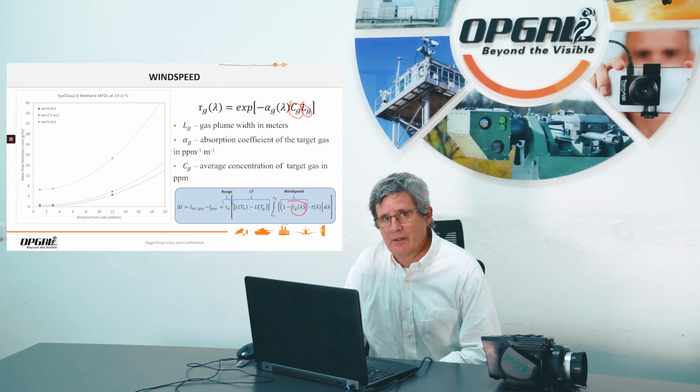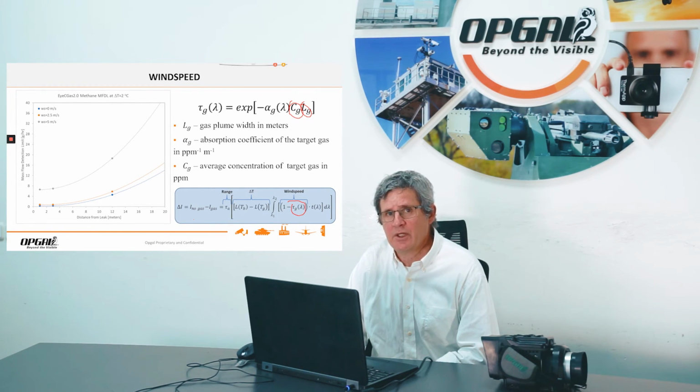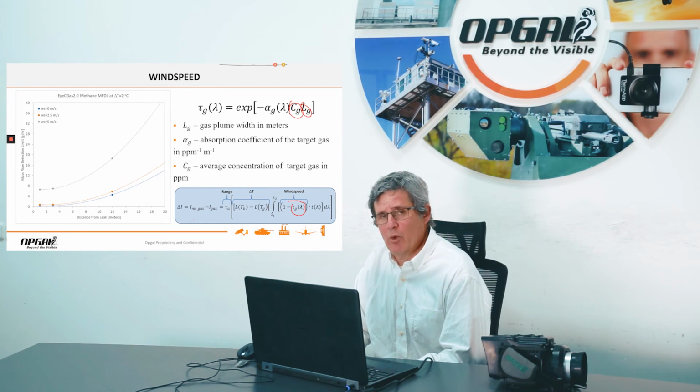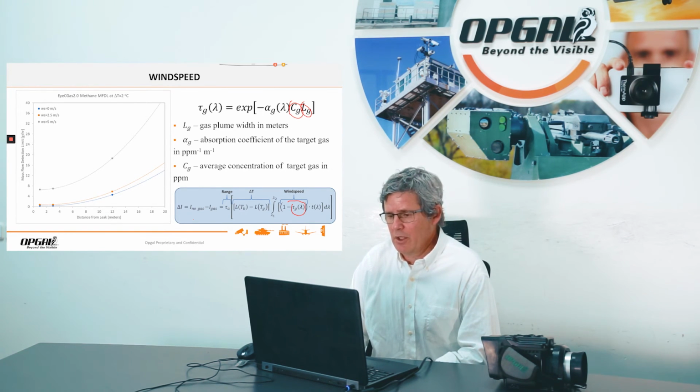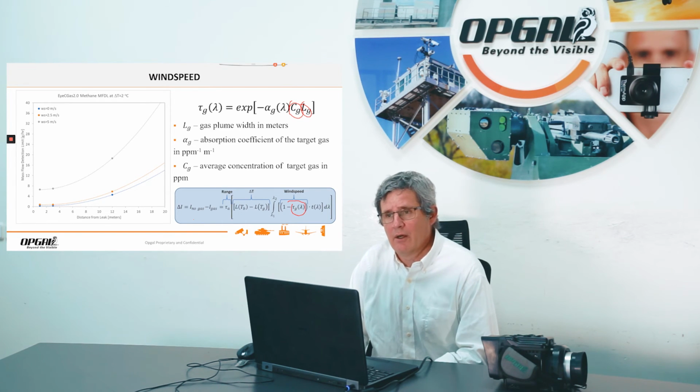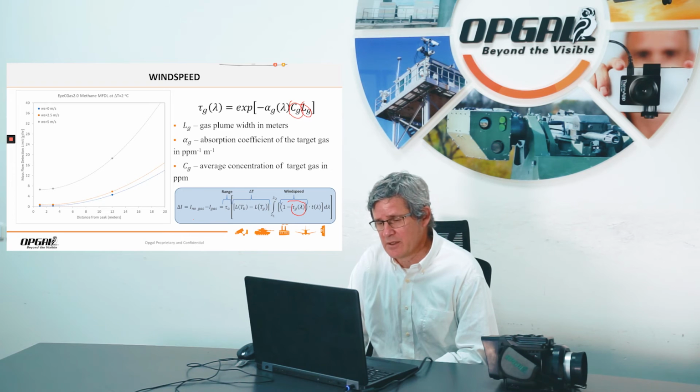We can detect and visualize plumes at 0.35 grams per hour. This is a very small amount, and if the temperature difference is larger, we can even see it in greater sensitivity. It can go to 0.1 or even less gram per hour for methane at this distance.